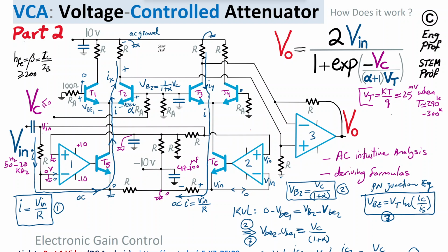So let me just show it. It means as if this is open and we have this connection, for example. So the circuit looks like this. From the perspective of op-amp 3, what it looks like is a connection from output through this resistor to ground. That's it. So effectively, since we have a voltage at the positive terminal, from the perspective of what we generated at the positive terminal, the circuit looks exactly like a non-inverting amplifier for the third stage.